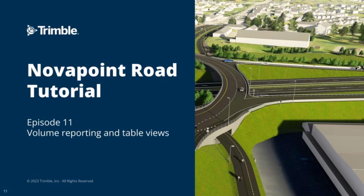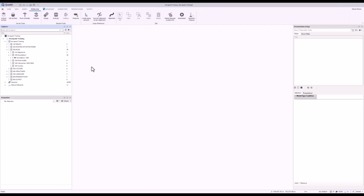In this step, we'll go through the volume tool and how we can use this to create a volume between the roadbed of our roundabout and the top surface, and then we'll add this to a table view to get a full takeoff from all the roads in the model.